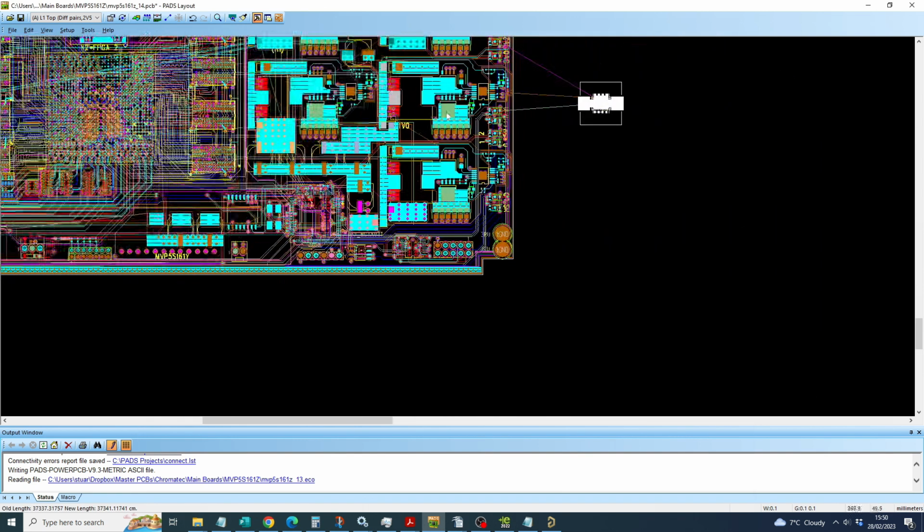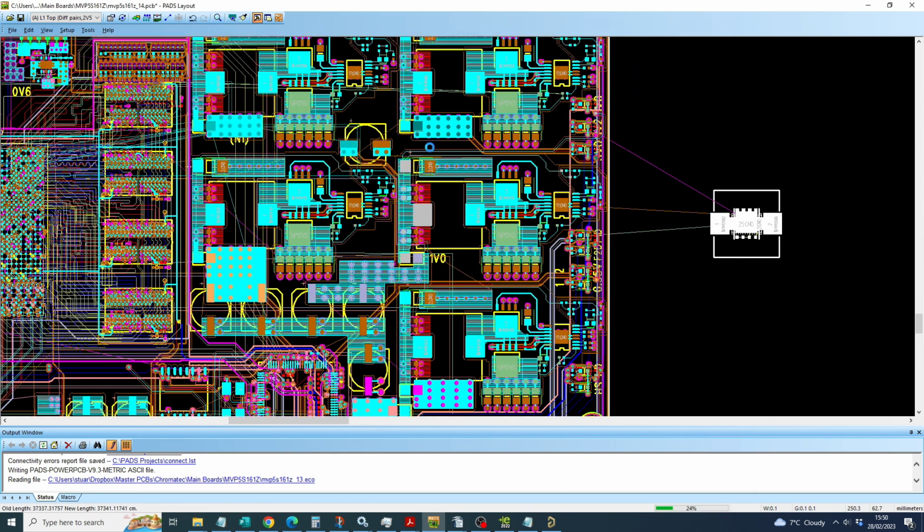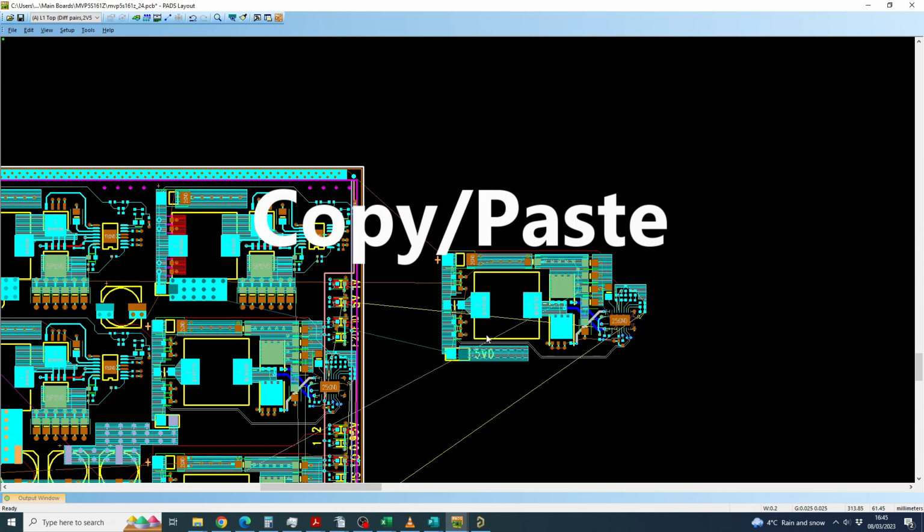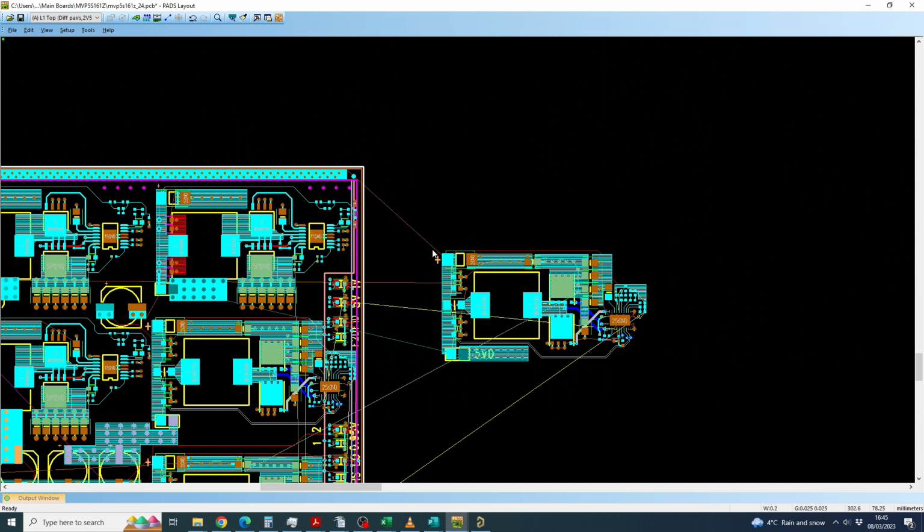This block of circuitry is going to replace one of these blocks, and then I'm going to duplicate it. In this case, we're going to copy this entire power supply circuit that's been carefully laid out, so we want to make sure it's copied in its entirety without any changes, and everything is just duplicated. So first thing we do is, it's easier to copy in the PCB layout and then back annotate the schematics with the new refdes information.